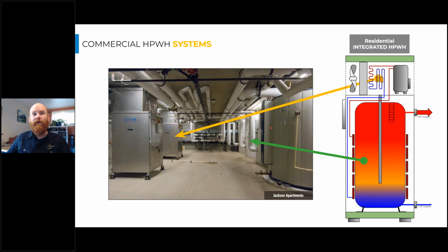So like we have a heat pump in our residential product, we also have it, of course, in our commercial built-up system. Same thing is true with the storage tanks. I said earlier that heat pumps are not instantaneous water heaters. It's a process. It takes time to move that heat into water. And so we typically will have a storage tank or multiple storage tanks, just as we do in that residential product. So here in the Jackson Apartment case, we have 3 white storage tanks back here on kind of the back right of that photo.